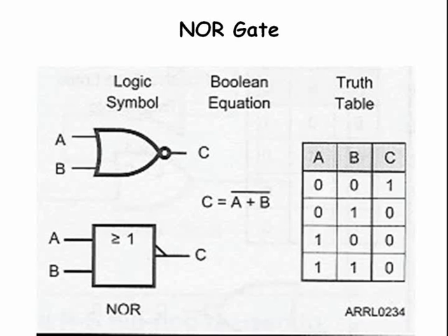The NOR operation results in a 0 on the output if any or all of the inputs are a 1. The logical operator NOR is usually denoted by a plus sign between the variables and a bar over the combination. Note that the NOR gate will have a 1 output only if all the inputs are a 0.